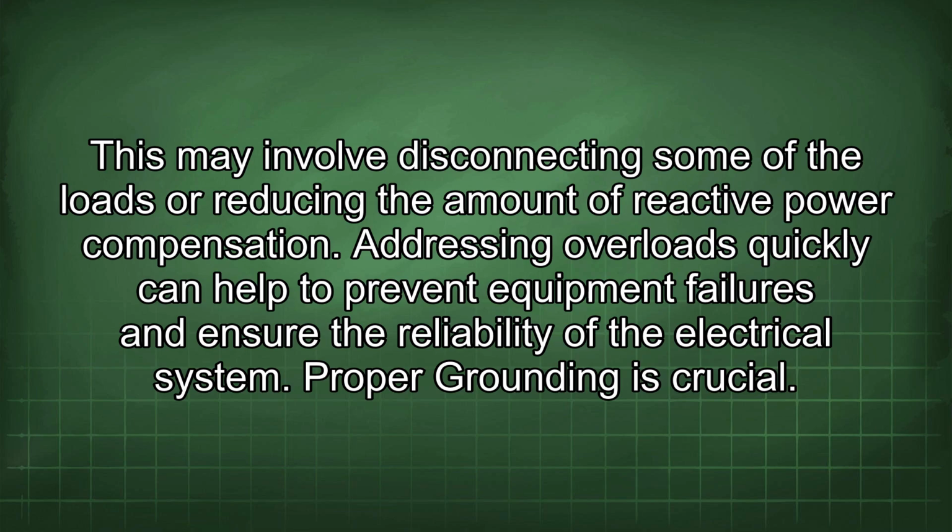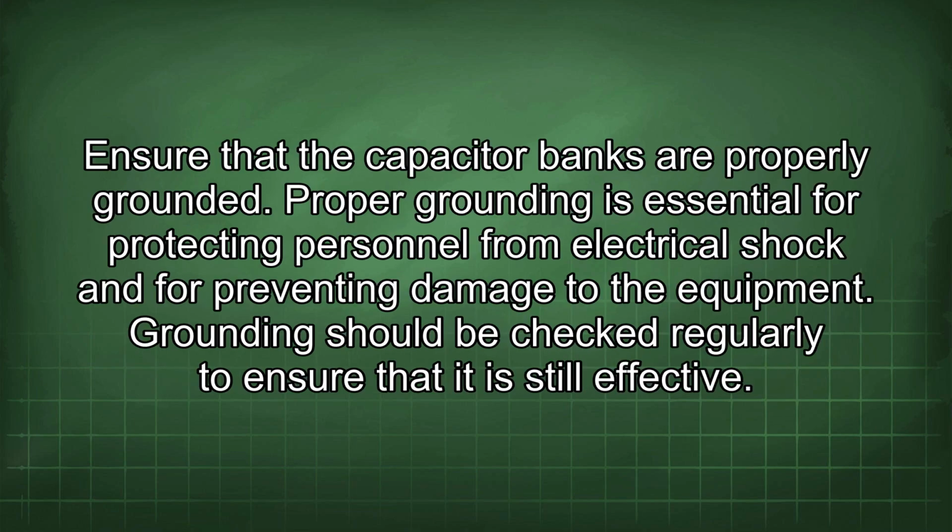Proper grounding is crucial. Ensure that the capacitor banks are properly grounded. Proper grounding is essential for protecting personnel from electrical shock and for preventing damage to the equipment. Grounding should be checked regularly to ensure that it is still effective.